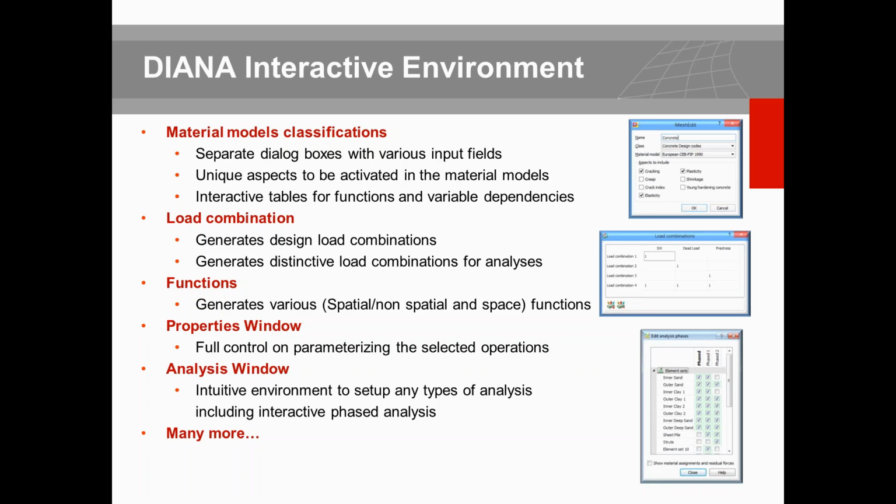Load combination is another dialog box which is available based on the label of the loads. You can introduce the new load combination before performing the analysis. We have introduced the concept of special and non-special and space functions. This is very important because you can define this spreading or variation of the properties or geometries in basically different dimensions, in 1, 2, or simultaneously on space, or you can introduce time-dependent or frequency-dependent functions.